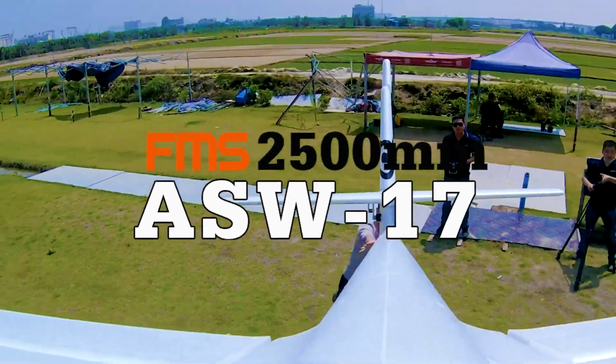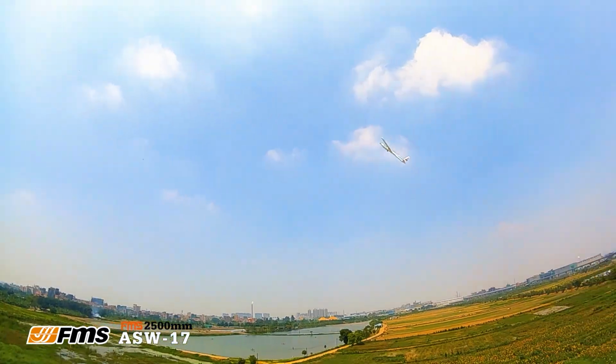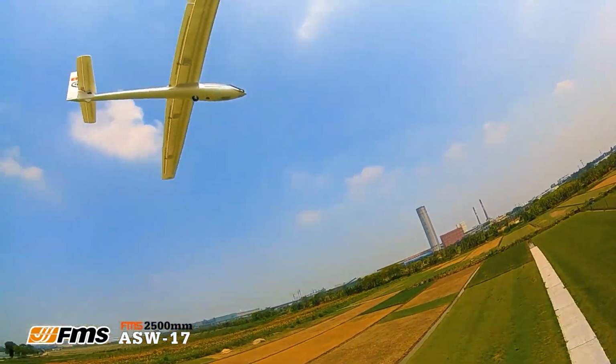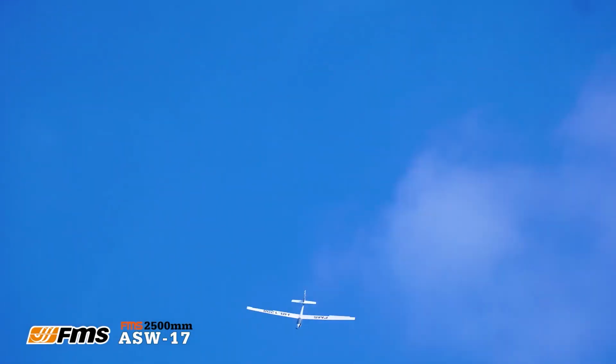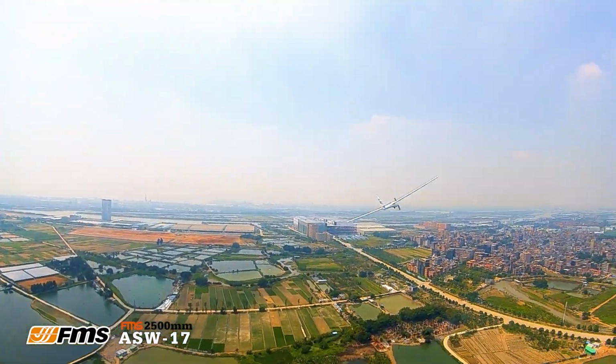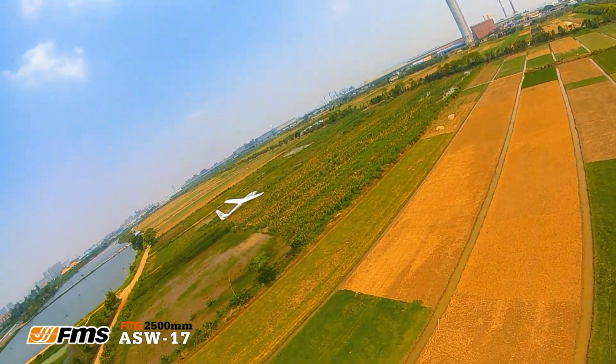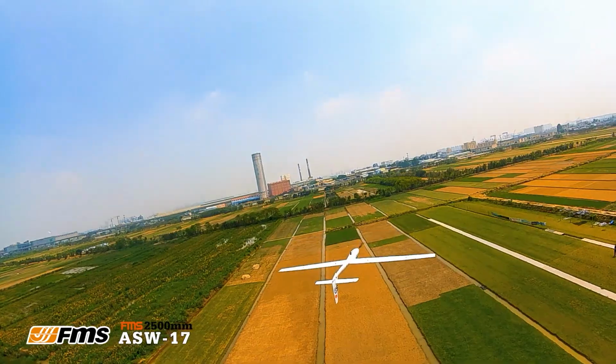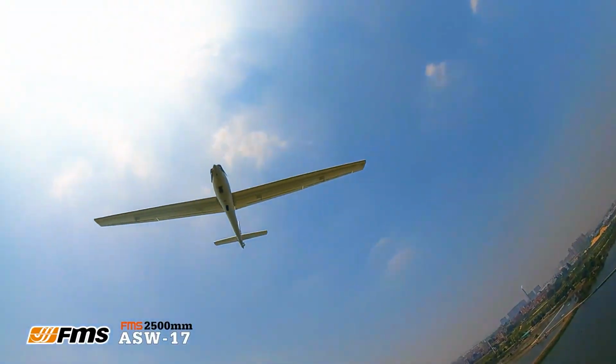As for the aircraft, we were given, obviously, aircraft number 4, better known to us as the ASW-17 EP glider, which is commercially sold by FMS, a company that manufactures RC cars and planes. It's a small electric-powered sailplane kind of glider characterized by a high aspect ratio and low wing loading. These characteristics yield high motor efficiency, high soaring efficiency, and very low sink rates, allowing for much better glide.